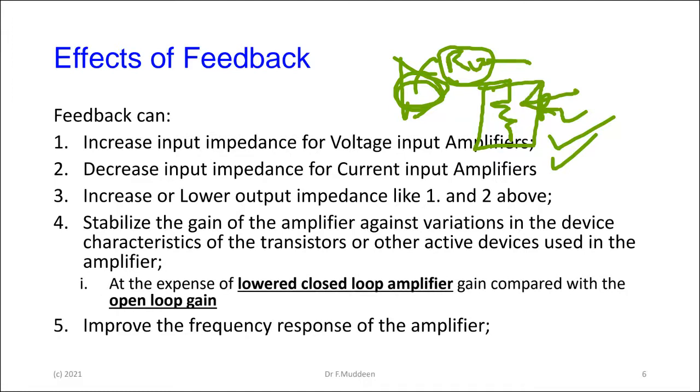And in the case of the amplifiers that are supplying the output current, you want the output impedance to be as high as possible, so that you develop as big a voltage as possible on the output going forward. So we looked at that, and then the last 2 things that we have to look at would be the gain, to stabilize the gain and to improve the frequency response of it. And there's a little bit here, and we're going to see that appear when we talk about the impedances here.